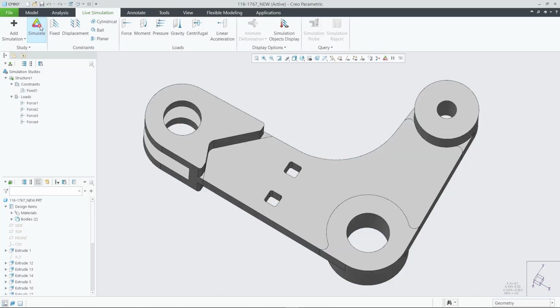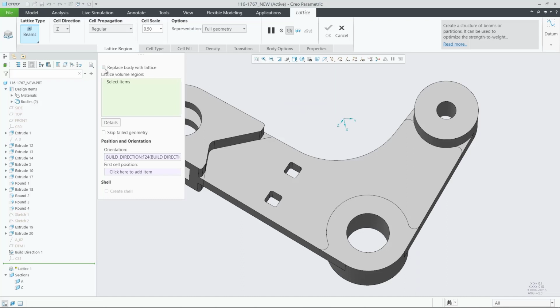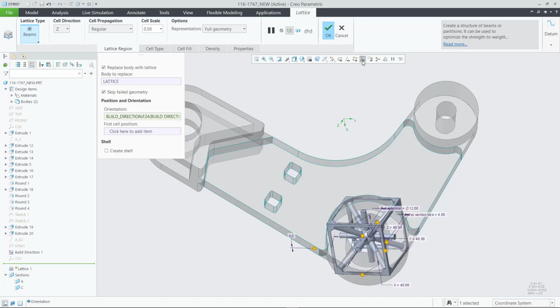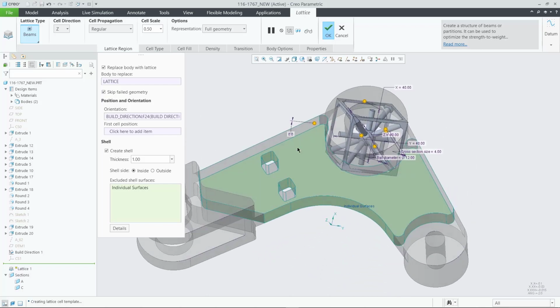Because what we're going to do is we're going to make this part out of 3D printed part, and I'm going to use that to take advantage of a lattice design. So Creo Additive Manufacturing has some really, really powerful capabilities to do designed-in lattices. And again, that's not something the printer is doing. This is saying, I want to make this a structural part of this piece. So I define basically what do I want that lattice to do. I want to shell out the whole model, or in this case, the whole body for the center section.